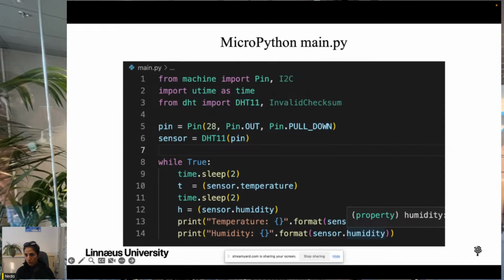And this helps to stabilize the circuit and ensure that the pin behaves predictably. So when we use Pin.PULL_DOWN in our code, we are telling the microcontroller to enable a pull-down resistor on that particular pin. And this can be useful in situations where we want to ensure that a pin is at a known and low voltage level when it is not being used.